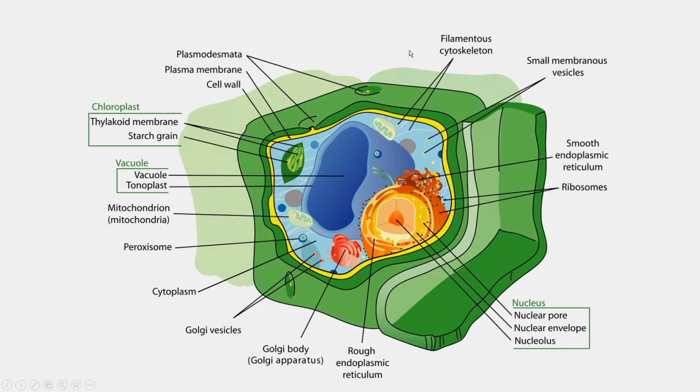And then additionally, in wood cells, these cells are stretched out axially, so they're not nice and simple and square around. They're actually very long. The typical cells that give wood structure are very long cells, and their length is stretched out along the grain of the wood, and in the trunk of a tree that will typically run vertically, and in the branches of a tree that will typically run along with the branch, although there are some exceptions, of course. And when I say stretched out, I simply mean that the diameter of the tree cells is much less than the length of them.